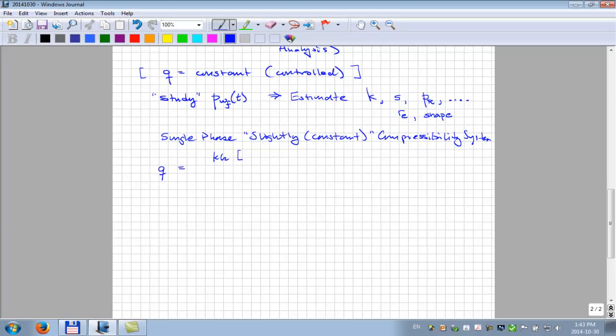If you set up the differential equations describing flow, which combines the Darcy equation with the material balance in a differential form, then you get pressure here. But now we're not going to use average volumetric pressure because we haven't started depleting. We don't have a volume to average over because it's an infinite acting behavior, right?